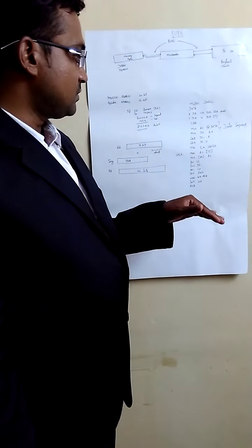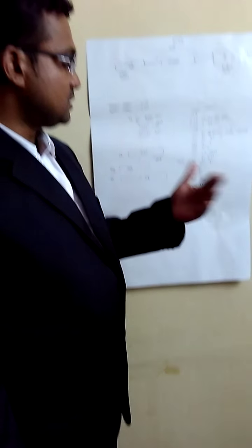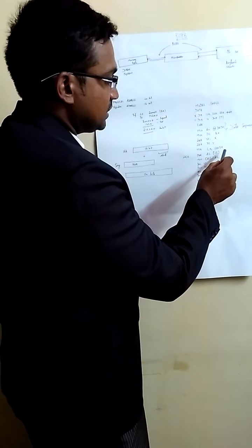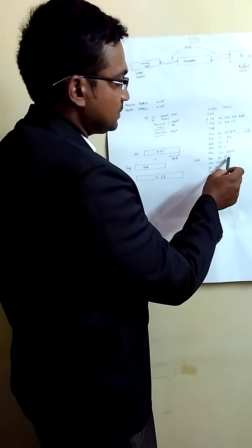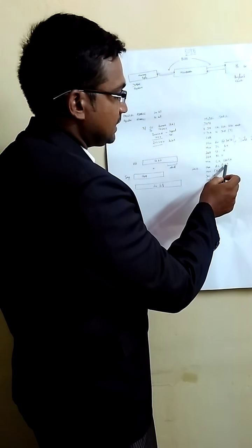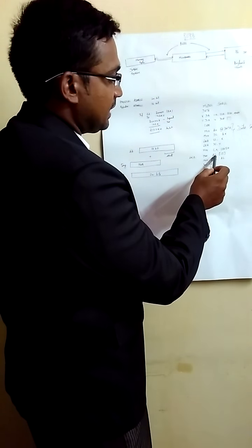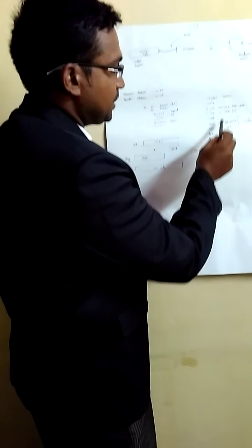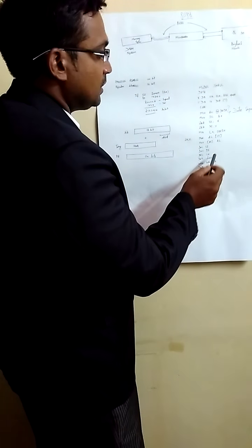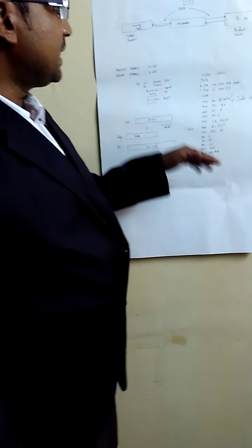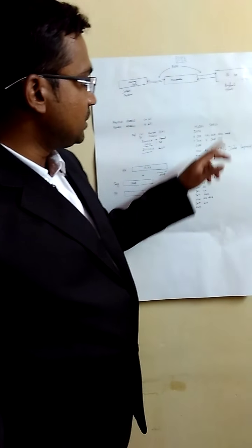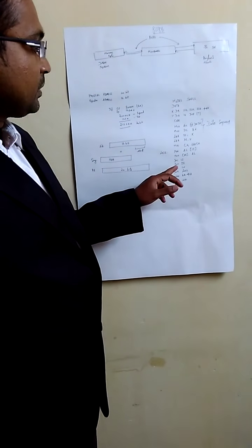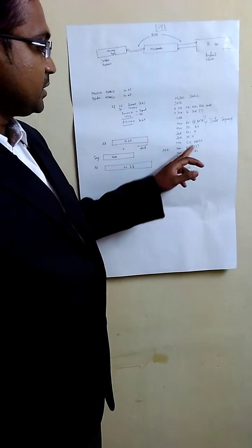After taking the CX value, you are now going to exchange the value. The content of the SI, this is register indirect addressing mode, that is the 11H, is copied to the AL. Following that, the AL content 11H is copied to the first memory location. After that we are incrementing the SI. Now it will be pointing to 22H. Next we increment the DI, the second value of the Y. Next we decrement the CX, which becomes 3.